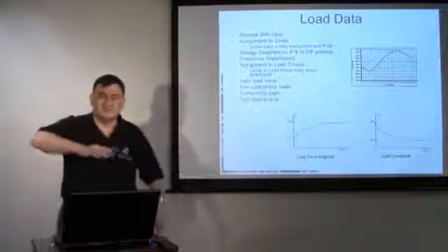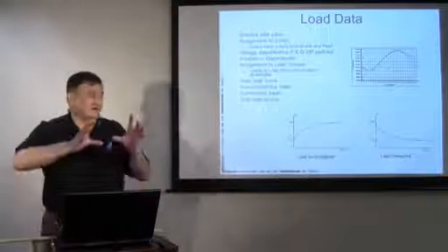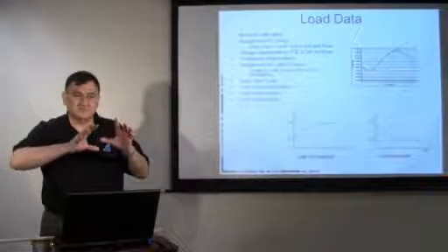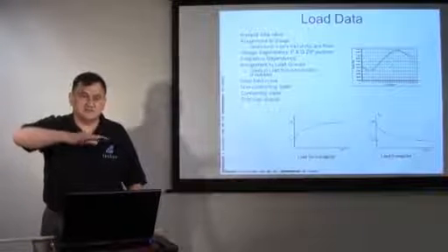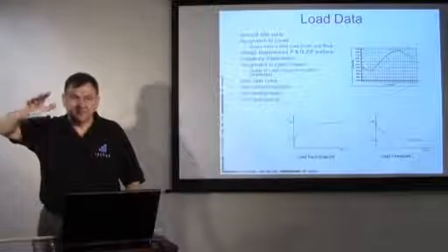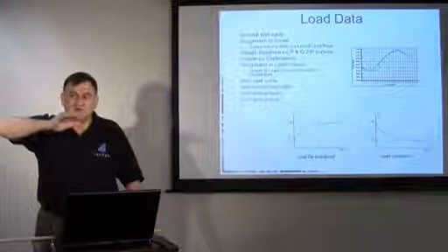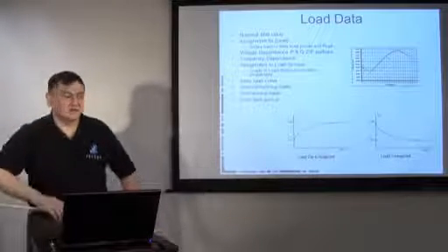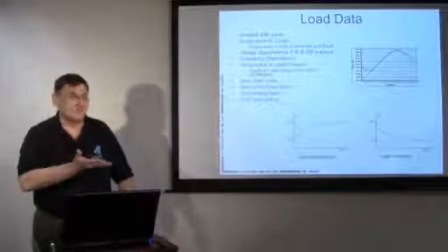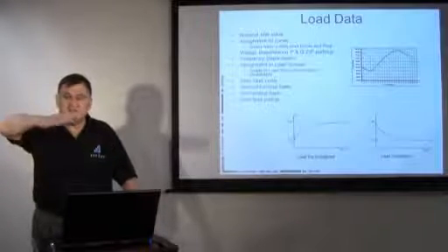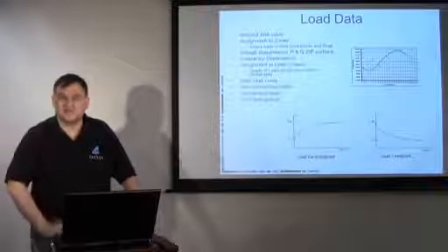What happens over time is that you lose the diversity. Let's say it's a hot summer day and a whole subdivision is blacked out. What's happening to the temperature of all those homes? The temperature is rising, isn't it? So let's say you're blacked out on a hot summer day for 2 hours. When that power comes back on, the load is going to come on at a much higher level because all of those thermostats, the temperature's gotten up to 90 degrees, and all of those air conditioners are all going to come on at the exact same time.